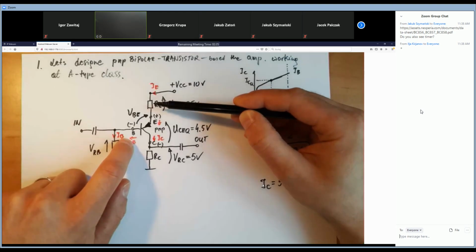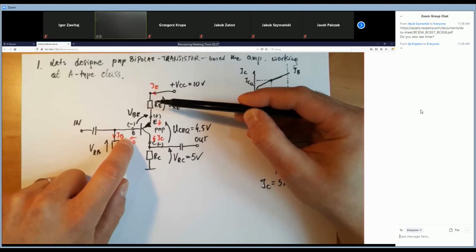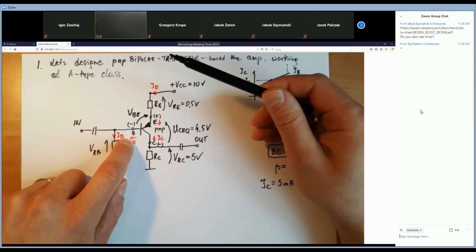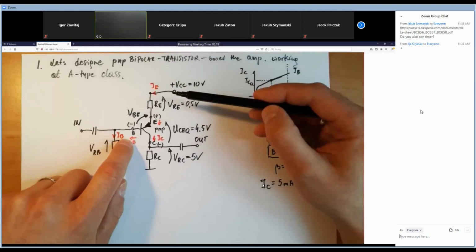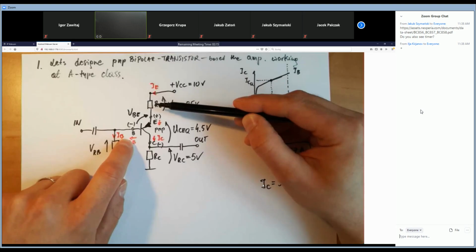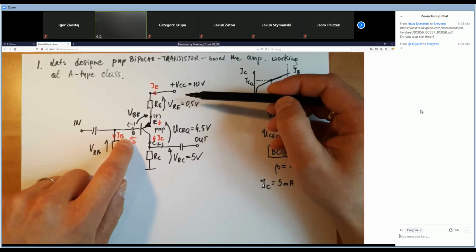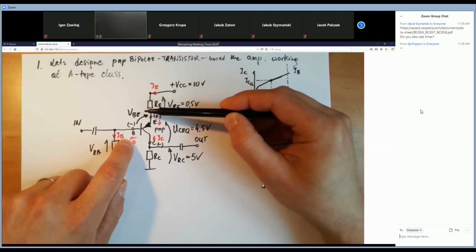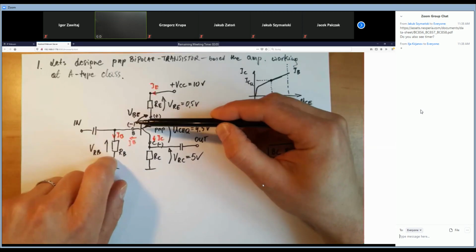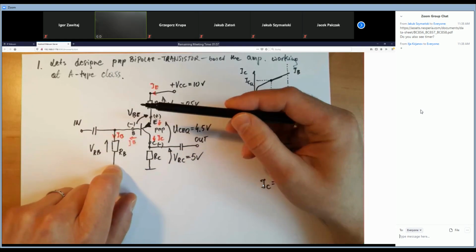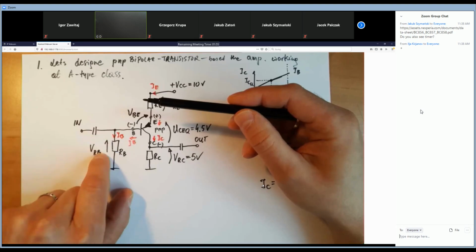If it will happen in that form, I think when the temperature is going up, the resistance of the resistor is going up too. So the voltage drop on this resistor will be going up. So for a stable UBE voltage drop, the voltage on the RB should be changed.